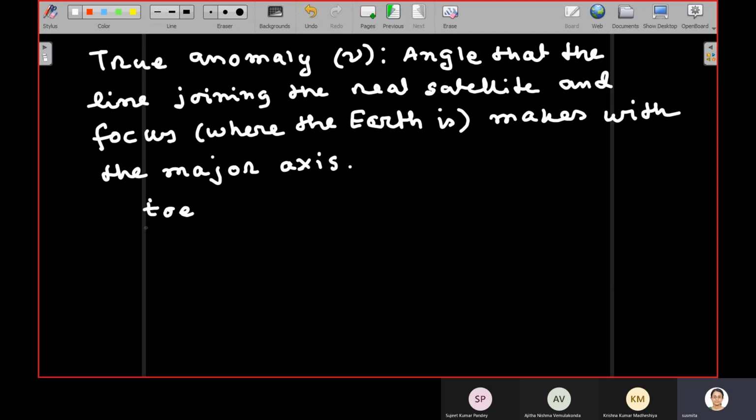Okay, so this time remains fixed over that 2-hour period. But if we want to find the satellite position, so time of ephemeris TOE is this time. Now we want to find satellite position at some other time, right? Because we have this 2-hour window, and within this 2 hours any time we can pick and find the satellite position.